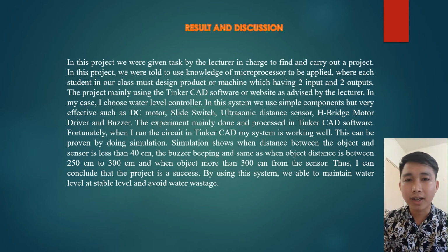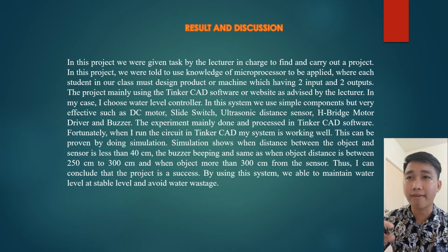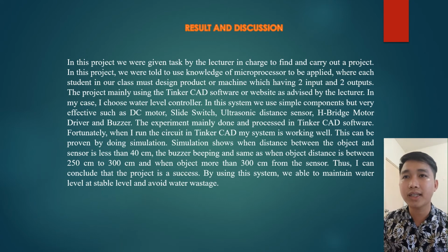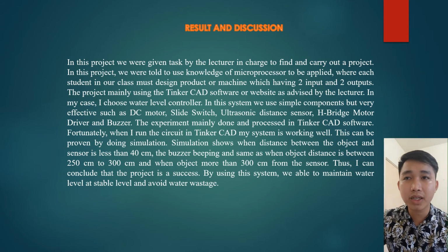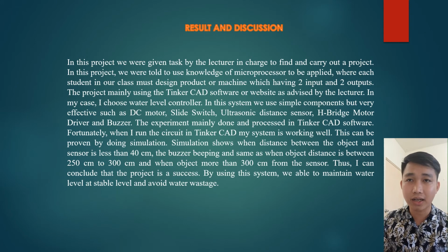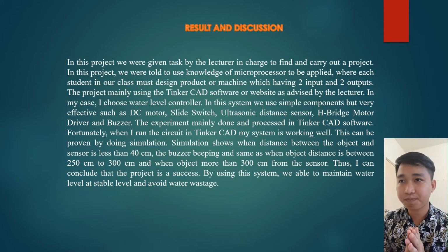And in my case, I chose the water level controller, and I use devices such as a DC motor, slide switch, ultrasonic distance sensor, H-bridge motor driver, and buzzer as the main components. And the experiment is mainly done and processed in the Tinkercad software or website.